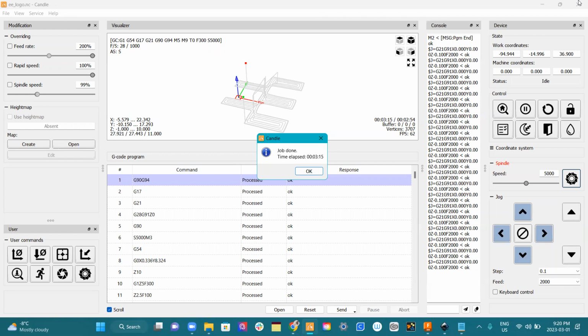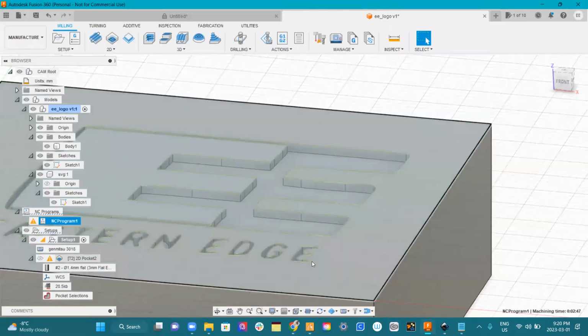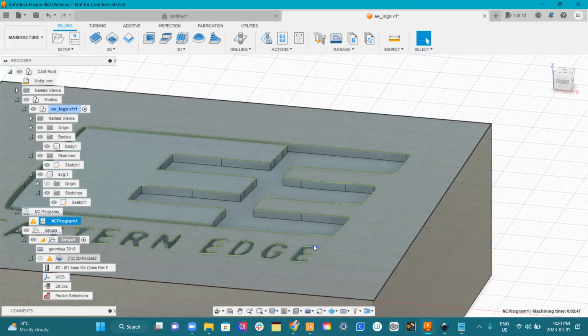This is to set it up. Now, when I set it up, it was right in the center of this thing here, and looking at the logo, I need to do this again. I've got a drill bit of a certain size that I need to fit in here, so I need to make the logo bigger. Also, looking at the logo, it goes over about this far, so I think it was actually fine for the alignment. The origin was good, the rest of it was good. It's just too small. I can also get a feeling for it; I was trying to avoid the clamping, but if I did the thing with the tape, there's a tape here, and then you can tape it right down to the bed or to the wood.